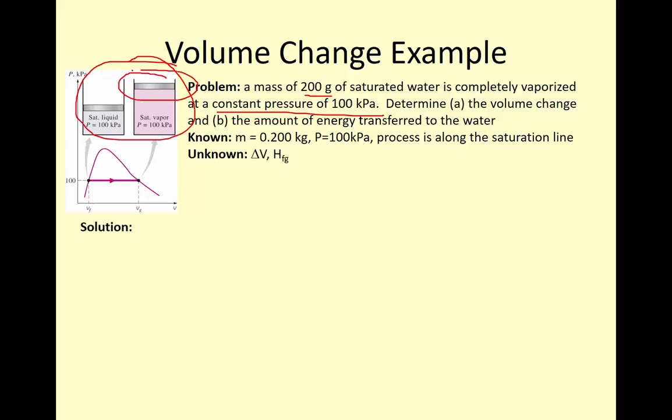So if this piston is free floating and allowed to expand as the gases expand, then we can add heat to this system and the gases expand freely without any additional restriction. We're assuming that this pressure is balanced by this piston on top right here. So the pressure is maintained constant while we add energy to this system.